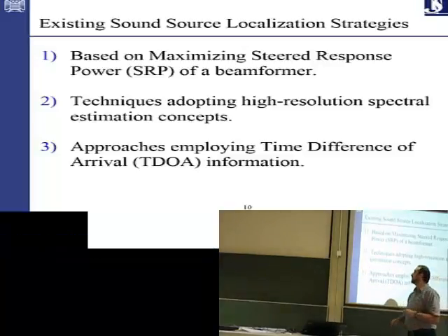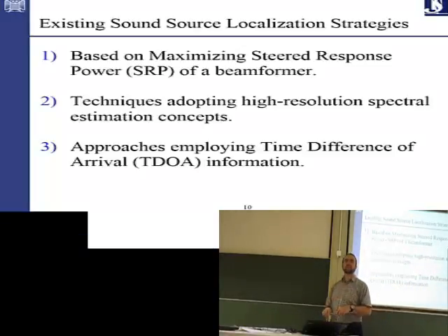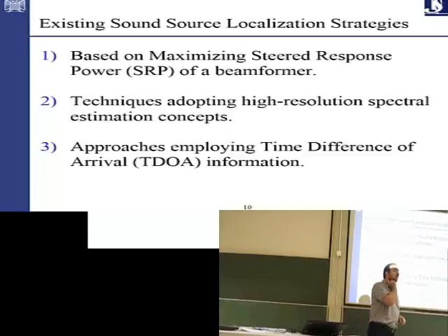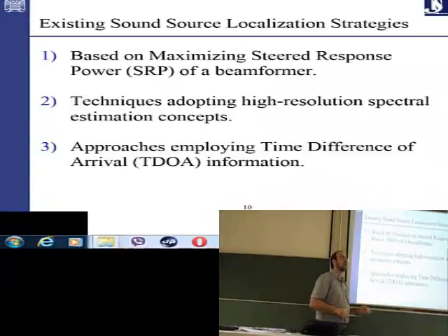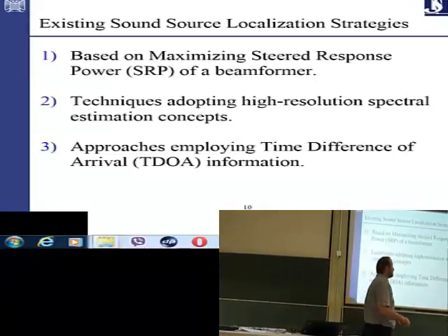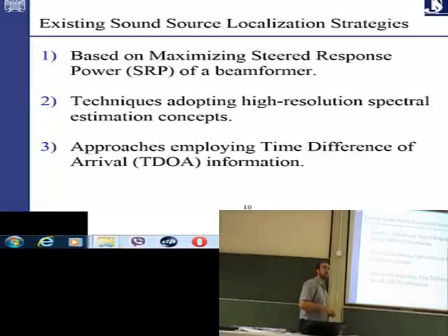It's a very good method, specifically when it comes with the phase transform compensation. It's called SRP-PHAT. It's almost the best localization method found today, but it's costly. And most of the time it's not possible to apply this in real time tracking.